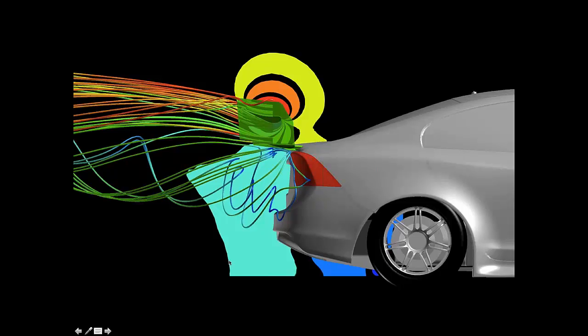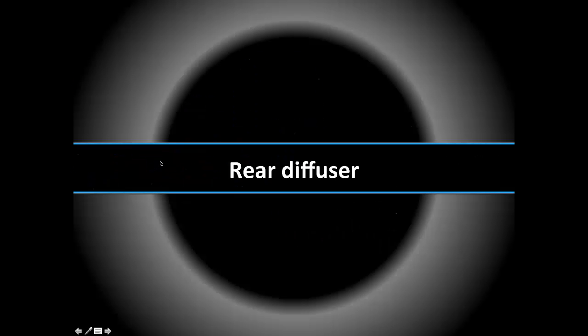One big thing with an end plate is you're generally sealing your high and low pressure regions away from each other, so you don't get vortexes intertwining, I guess, on the side of your wing and lowering its efficiency. So it's a good way for race cars to increase wing efficiency.